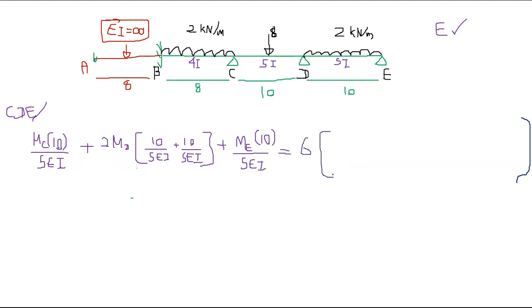So I will not write the settlement part, 0. There's a load here, right? So the point load. You remember that's WL1 squared over 8, the area of the simply supported bending moment diagram, right?